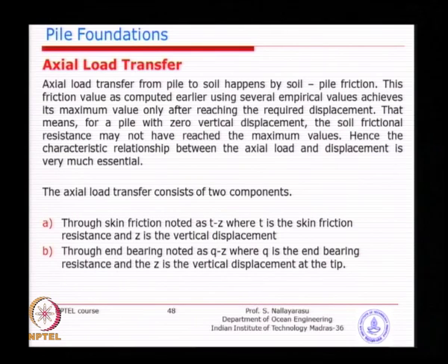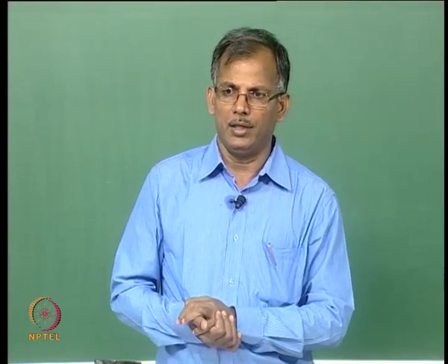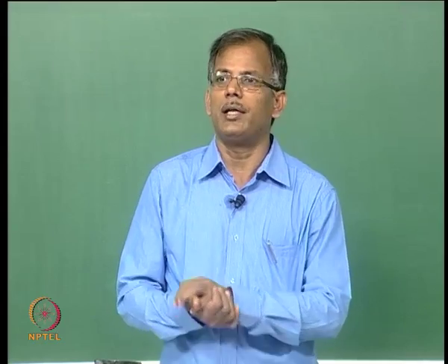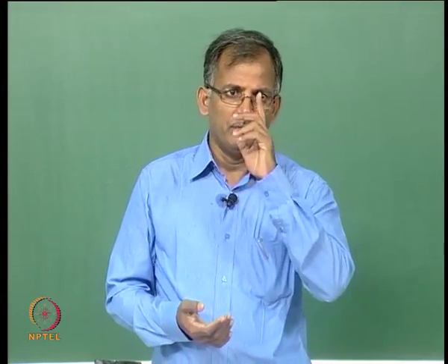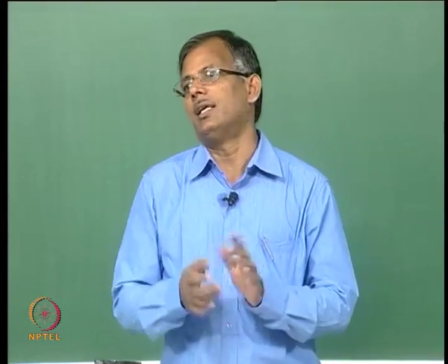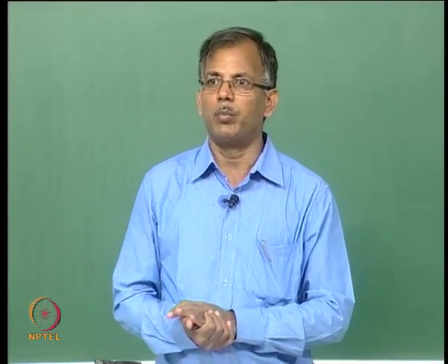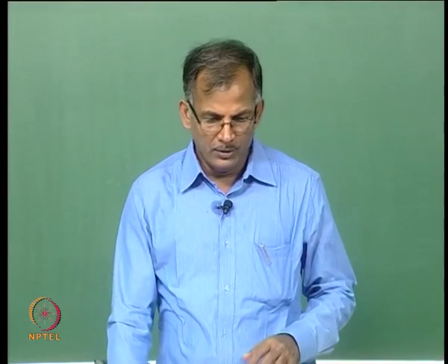If it is like steel, you will expect a straight line, but you may not get that, because the behavior is definitely non-linear, and that is where we find that the problem of interaction between structure and soil is slightly complex compared to other analyses. So, you need to do a non-linear response analysis. That means, if you have a displacement of 1 mm for 1 kilonewton, it is not that you get 10 mm for 10 kilonewton; it is going to be non-linear, not a linear proposition. So, that is what we are trying to establish.